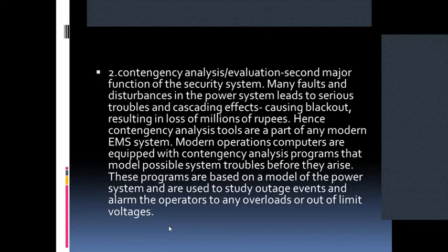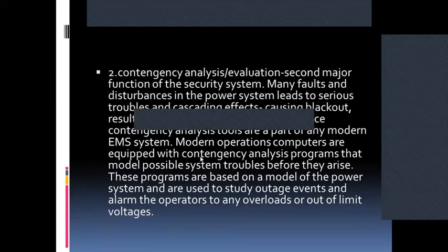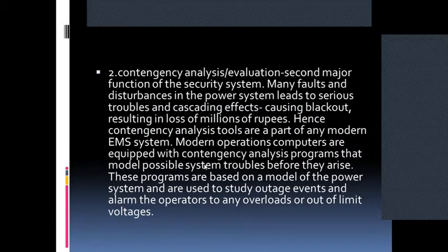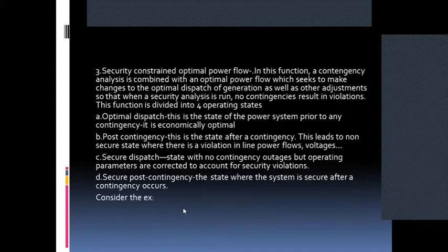It should happen, so we have to do the analysis. Using a simulation package, this analysis can be done. Modern operations computers are equipped with contingency analysis programs which model possible system troubles before they arise. These programs are based on a model of the power system and are used to study outage events and alarm the operators to any overloads or out of limit voltages.